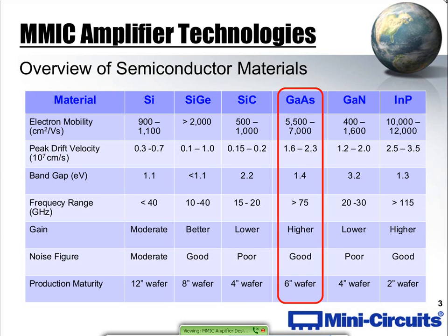So maybe this is not important for every application, but if you're operating on batteries or in remote applications like automated meter reading where you're dormant for days and weeks at a time, and then you have to transmit and a battery has to last years, silicon germanium has really found a home and is a great alternative to pure silicon or some of the higher current consumption technologies like gallium arsenide.